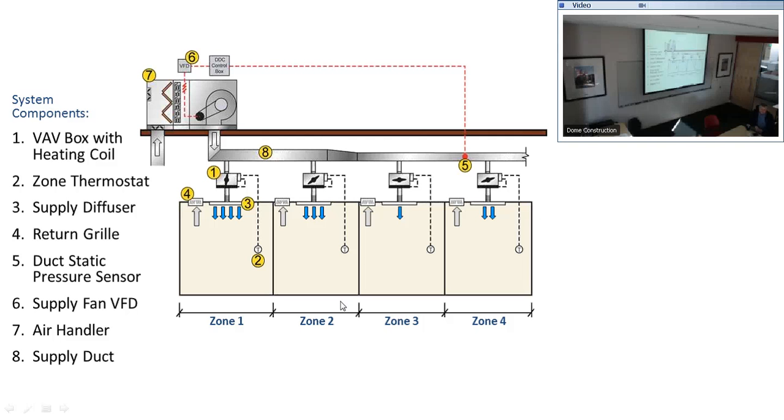A lot of times you're never going to see condensate come out because the coil has to hit dew point, so you have to have conditions in the outside air with moisture above what we call dew point. So at probably around here, 80, you're not condensing any moisture.